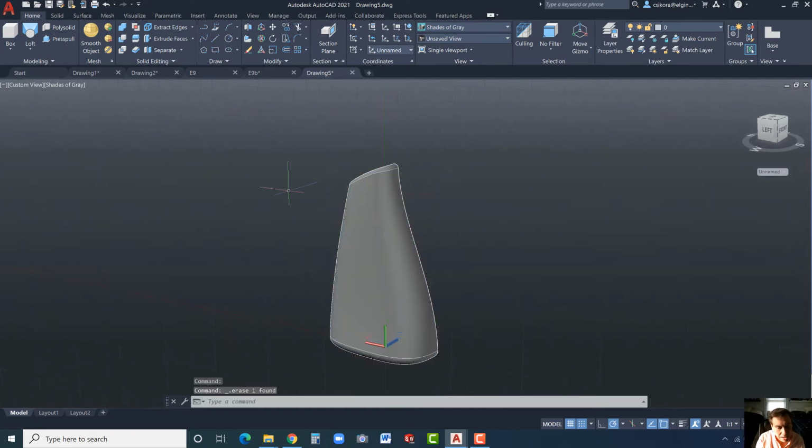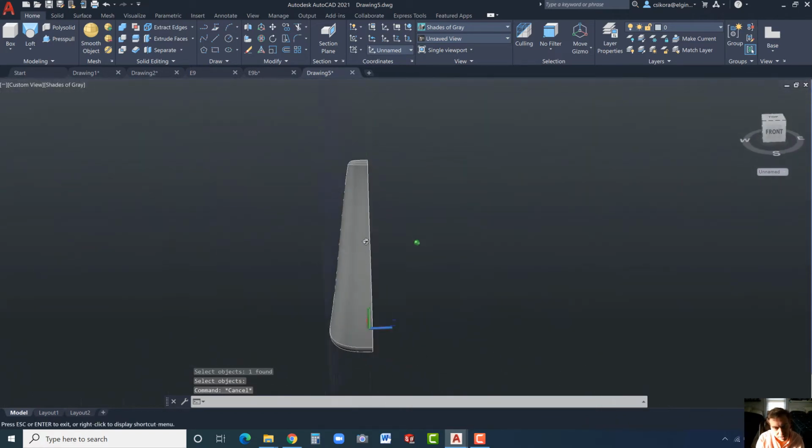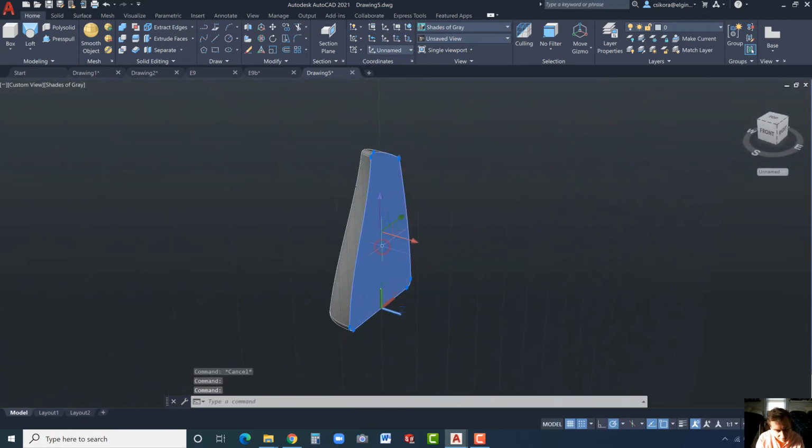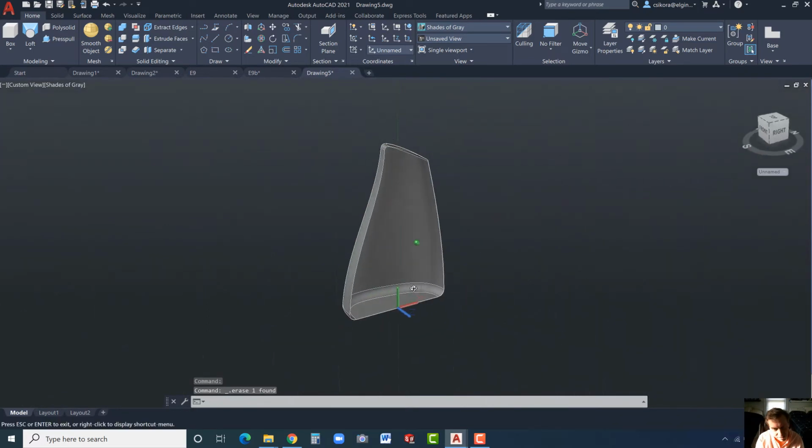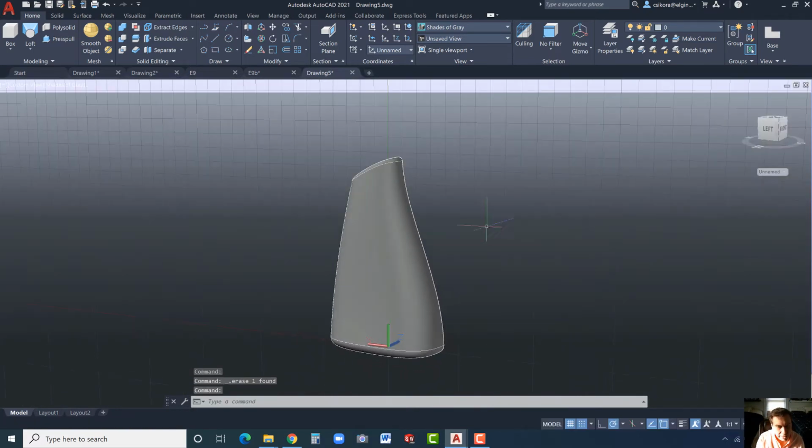All right. And I'm going to go ahead, and now I'm going to change this into surfaces. So I'm going to go modify and explode it. So go to explode, select the model, hit enter. Now it's a collection of surfaces. We don't need this back surface, so you could click on that and hit delete. You can see it's hollowed out now. All right. So technically we could have done this from the very start with 1/2, but there is some security in making it smooth on both ends. So by the way we're doing it, I don't necessarily know if we need to do that though.